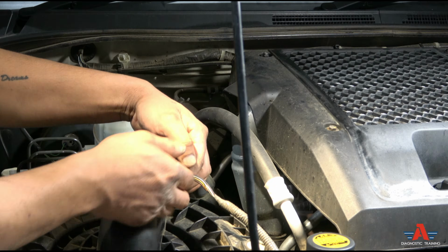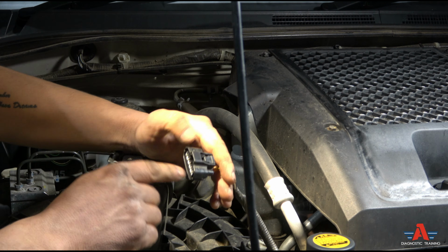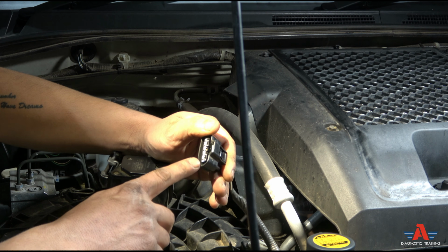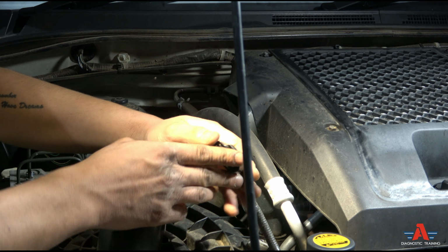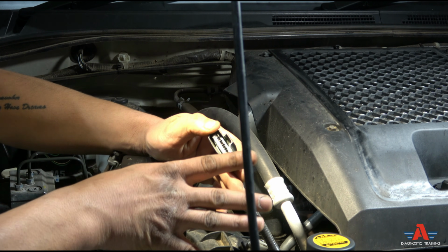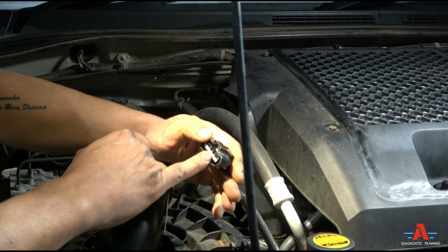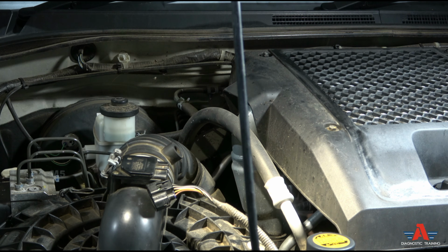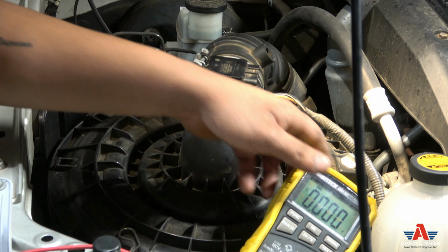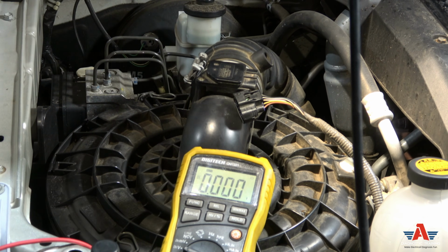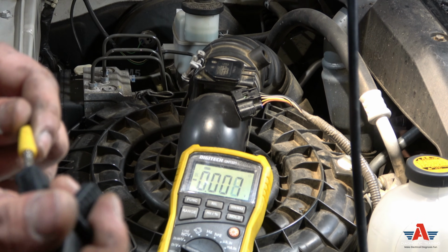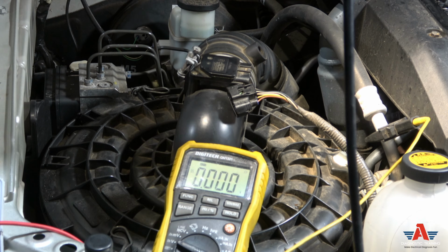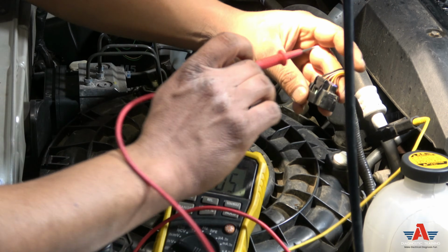All right. If you check the voltage and earth here, you're going to see exactly like the other sensor we did, the coolant temperature sensor. You're going to see 5 volt, and you're going to see earth. Exactly the same principle. There's no difference. Okay. Now, I've got to put my multimeter right here. Multimeter connected to battery negative. Okay, I'm just going to use my AC pipe there. It's a negative anyway.